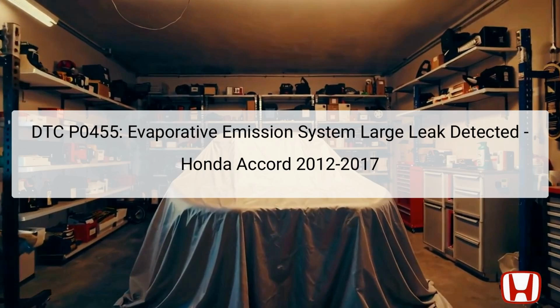The diagnostic trouble code DTC P0455 indicates a significant leak in the evaporative emission (EVAP) system of the Honda Accord, particularly from the K24W1 engine type manufactured between 2012 and 2017. The EVAP system is crucial for capturing fuel vapors emitted from the fuel tank and preventing them from escaping into the atmosphere. This system employs the engine-off natural vacuum (EONV) method to monitor fuel tank pressure using the fuel tank pressure (FTP) sensor when the engine is off.